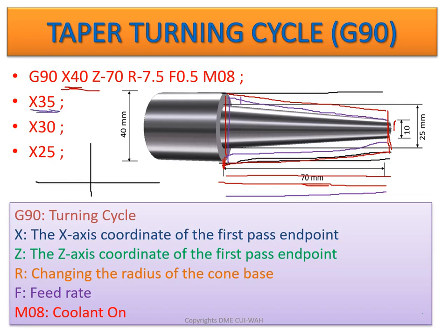In the next cycle, let me choose another color, the green line. Now the diameter at the left end will be 30 mm, x30, and removing from the right end, the first time it was 25, the second time it was 20, now the third time it will be 15 mm, removing 5 mm from both sides.